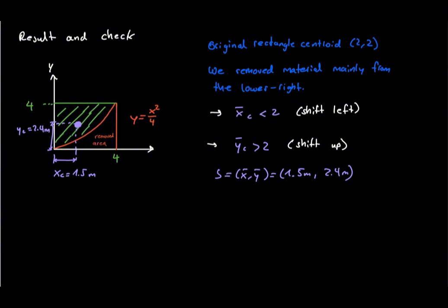The key lesson from this example is that the integral centroid formula is not a different concept from the composite area formula. With a few simple shapes, we use a sum. With a continuously varying shape, we divide the area into infinitely small pieces and use an integral. And when part of a composite area is removed, we simply treat that part as a negative area. This gives us a powerful method that we can now use for much more complicated centroid problems.